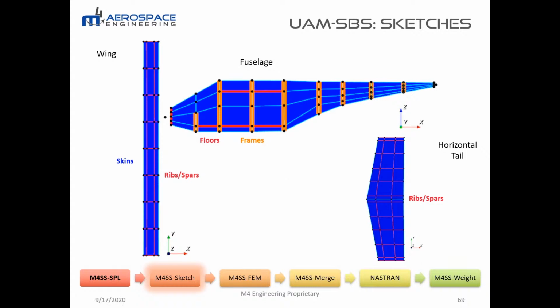So we've got a floor for the cabin, and then a ceiling, which is where some of our large masses are: an engine and those kinds of large mass items up there. And where we have the orange double lines, we're going to have ring frames. We're going to have a series of those that run through the fuselage.